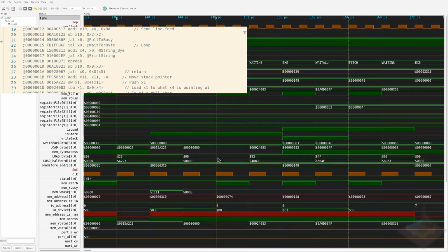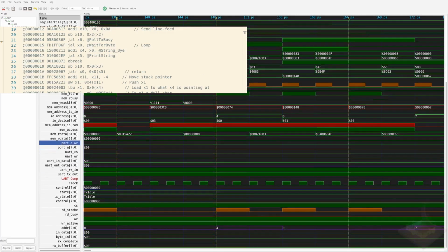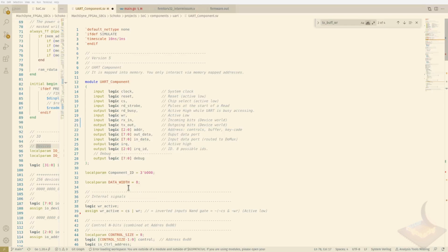We've covered this before, but I wanted to cover just the read strobe because it's very important for your devices when you're reading. Now the write has a slightly different characteristic where instead of a strobe, you're literally detecting an address, a chip select, and then you can see the write flag come out of the processor to indicate whether you're reading or writing. I just wanted to cover the read strobe real quick so that we knew what was going on with it, and that's it.